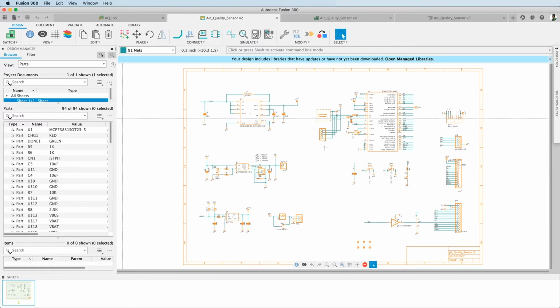Now Fusion works in the way usually you go from the left to the right. So on this menu bar here you see the menus. That's the switch icon where I go into the board. I have some general things like info and show, the grid command, layer related stuff. Then I have copy, paste and delete. And then the first real important command is the add command to add a part.